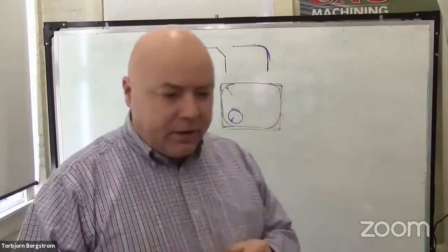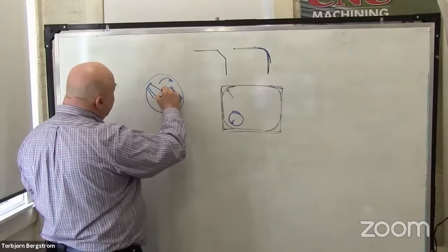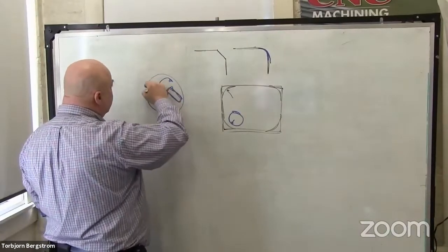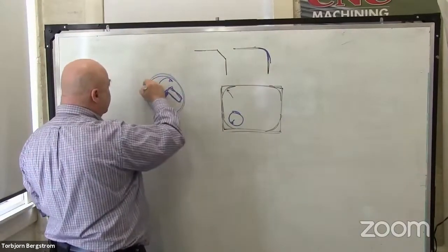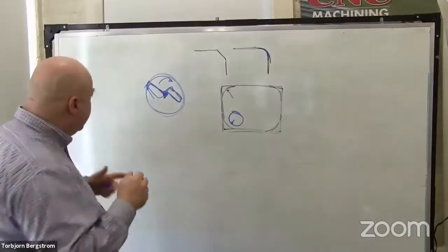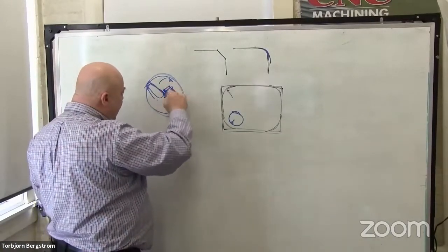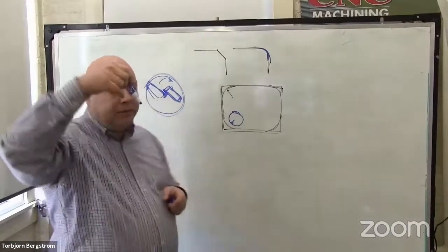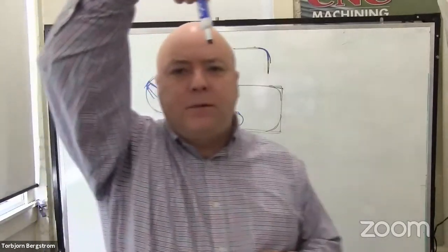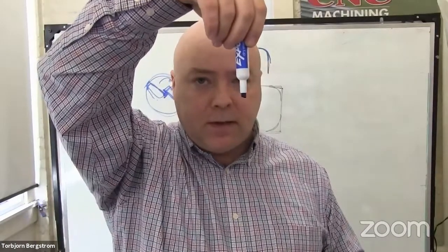What happens to the material at the center of the drill? It heats up and gets pushed out of the way. Now, as you come out the cutting edge here, the surface speed increases, and we can figure out what it is at any diameter based on the formulas that we have, right? So as we come out, but also because these tips overlap, what if you're not absolutely, 100% perfectly straight up and down when you push down on the drill and start spinning?